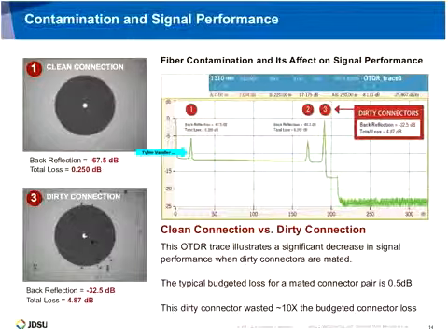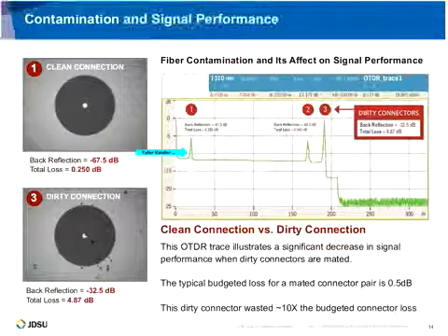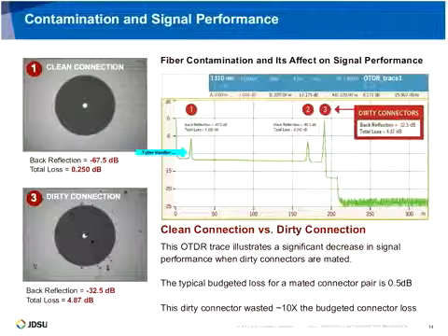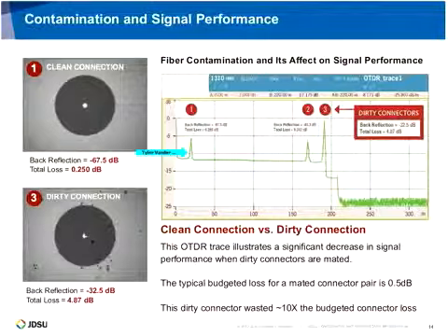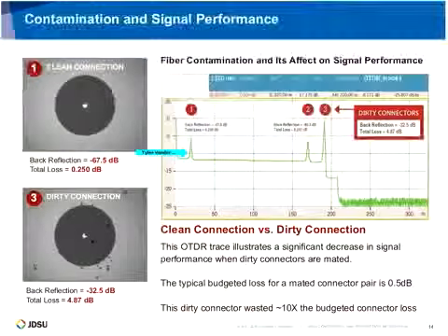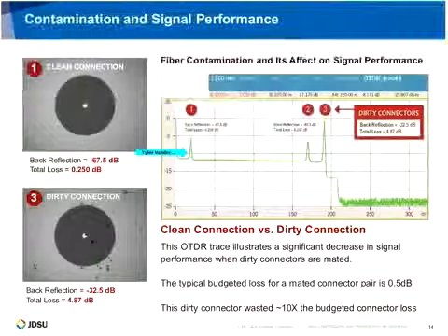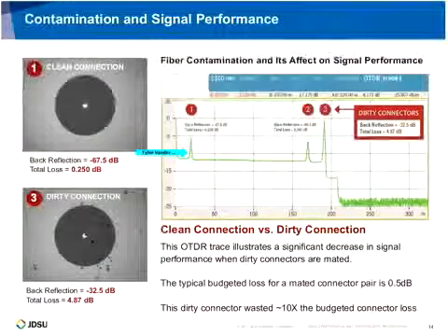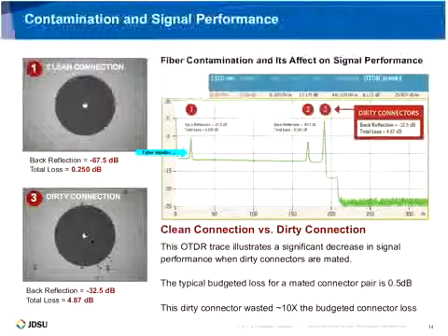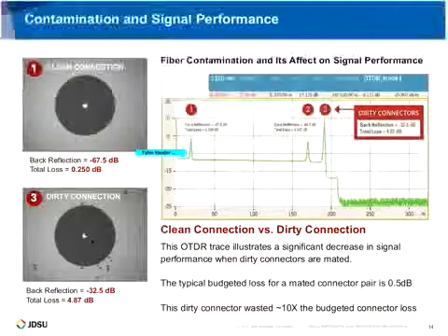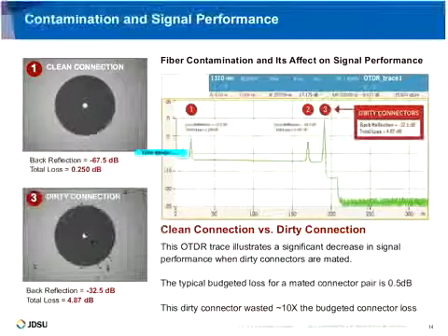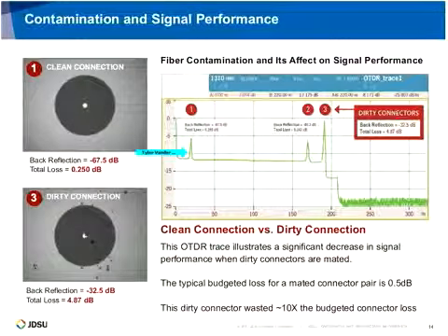And you'll notice here I put a couple numbers above some of these, and I included some screenshots of some of those numbers of the events. The first one here, that small spike, is an event that's caused by just a fiber connection. There are 2 fibers mated here, and you're always going to see a little spike whenever that happens. It's actually factored in. In fact, even when you're budgeting the loss, the typical loss budgeted is about ½ dB, just specifically for a mated connection. So that's factored into the budget, so you will see a little bit of a spike.